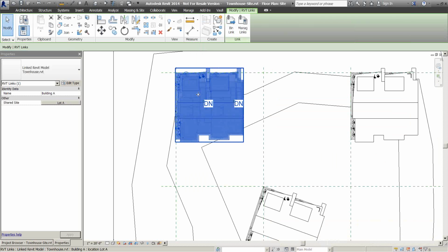What it's doing is using the origin point of the townhouse and saying that my townhouse origin point is, let's say, at the corner of this building right here, located specifically at this metes and bounds, our northing and easting and all that, at a certain elevation and a certain rotation. Okay, so all that's being recorded with that.